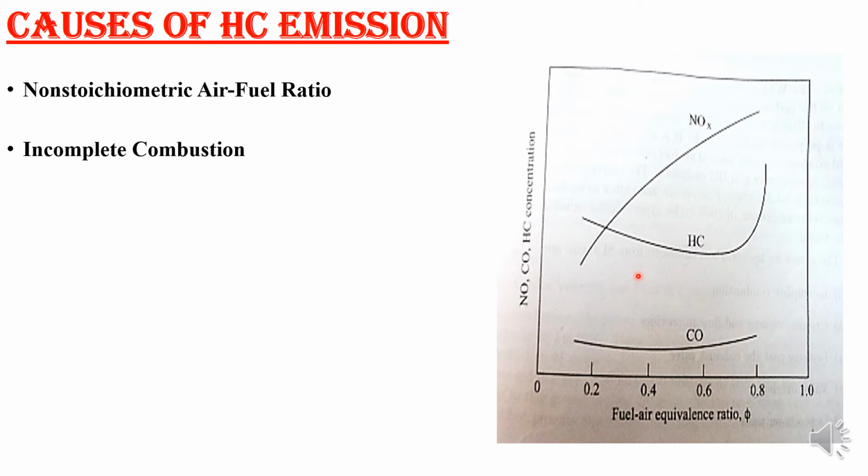So very little emission will be obtained at cruising condition. If we adopt the EGR system, then high levels of EGR will cause more HC emission also. It has been found that HC emission can be reduced if a twin spark plug is added in the combustion chamber. That is one of the new technologies you can see in the Pulsar. They have adopted twin spark technology in the bike.